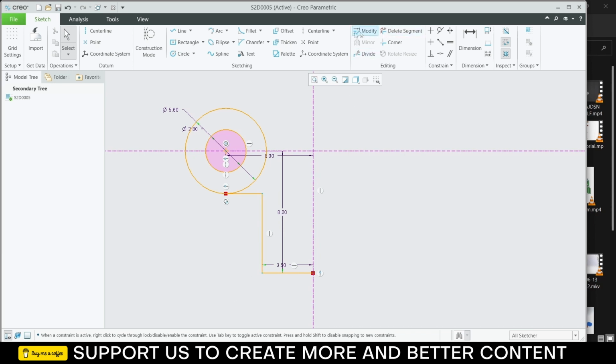Now let's use some fillet. Select this and this one. Click on dimensions, double click on it. This is 1, and this is 2. Draw a non-center rectangle, one rectangle like this. Click on the middle mouse button. Width is 3 and the length is 7.